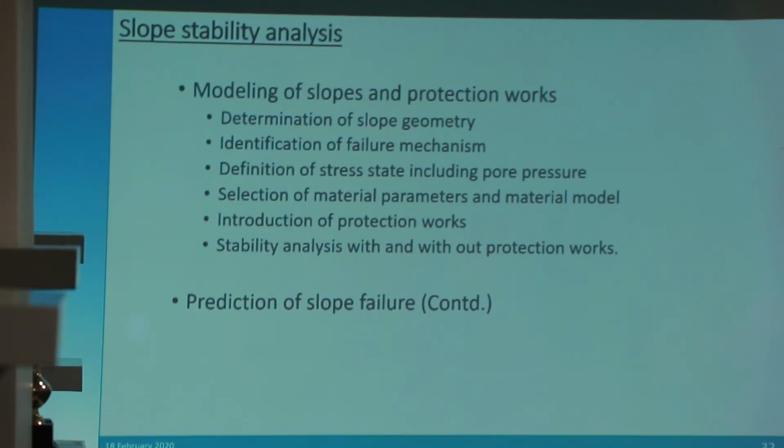And next, more important is the introduction of the protection work. And the last one should go back and forth with the introduction of the protection work. We have to check the stability analysis with and without protection work, and that should include the structural as well as, I'll say, the hydraulic stability, if it is in the valley.